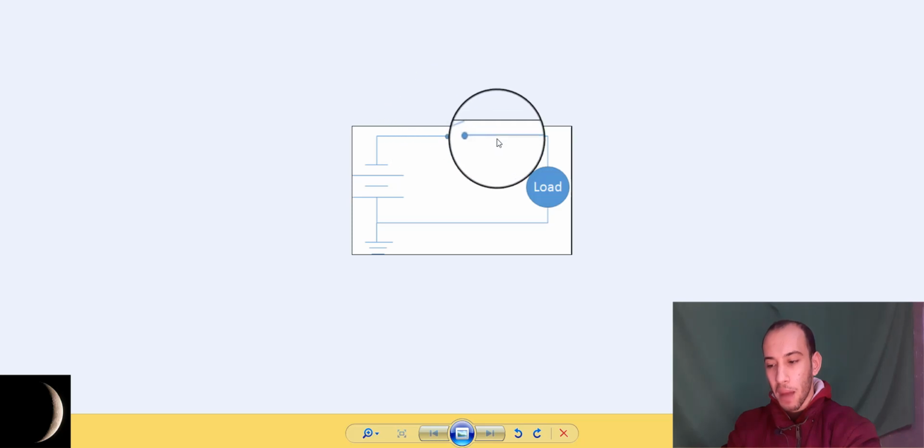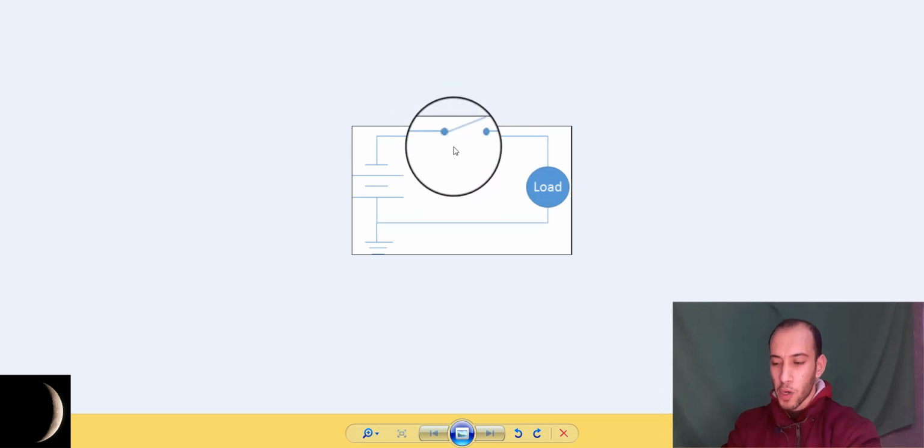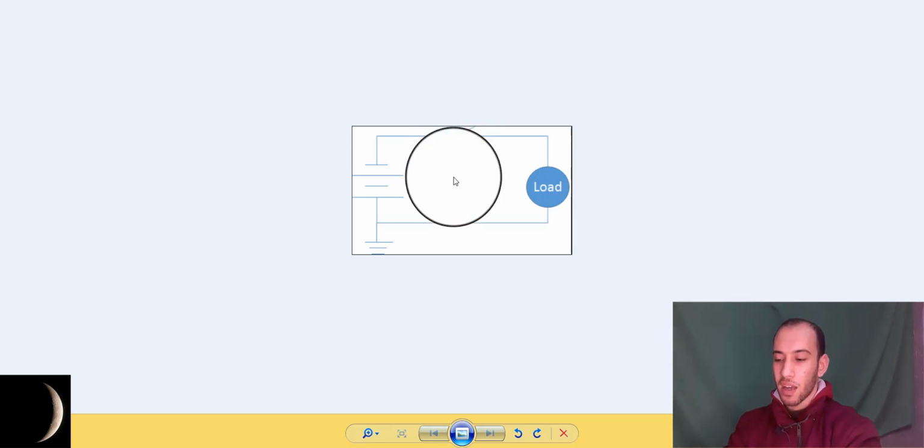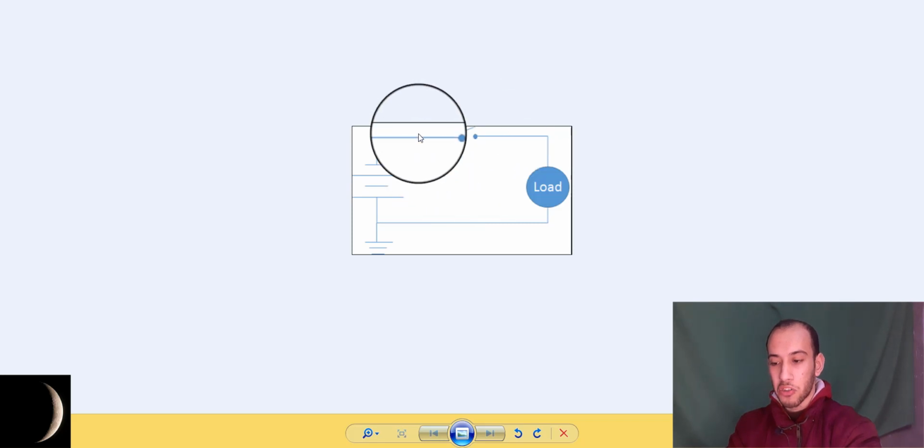And this is also happening to your power switch. This power switch is typically a MOSFET. So if the inrush current is higher than the maximum current the MOSFET can handle, the MOSFET will be burned out, or at least its lifespan will be shortened, especially if you don't have a snubber circuit across its terminals.